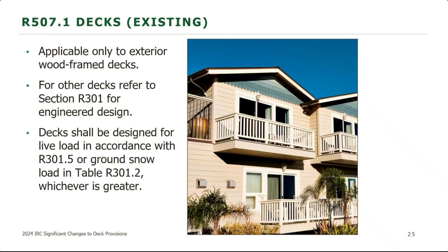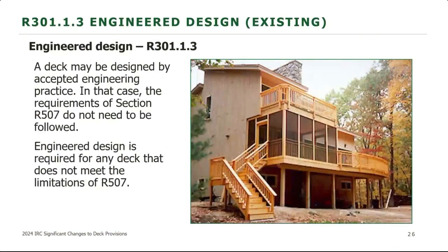If you want to frame it out of steel studs or other materials, you'll have to go through engineered design in accordance with R301. Same thing if you have higher point loads or exceed the span limitations in the code. And here is engineered design through R301.1.3. Again, that's an option then for designing a deck that doesn't fit into R507.